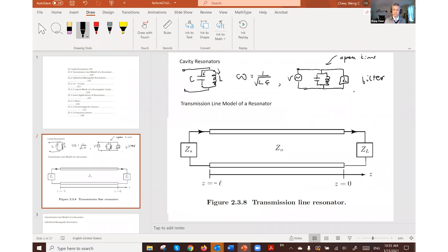And how do we make a resonator out of all the things that we have known now? We can start with the simplest resonator we can make from a transmission line. Just take this figure over here. If I were to have, this is not a source now, this is the impedance of the source, and this is the impedance of the load. And imagine a wave bouncing back and forth between the two ends. And imagine that these loads are lossless so that they don't absorb energy.